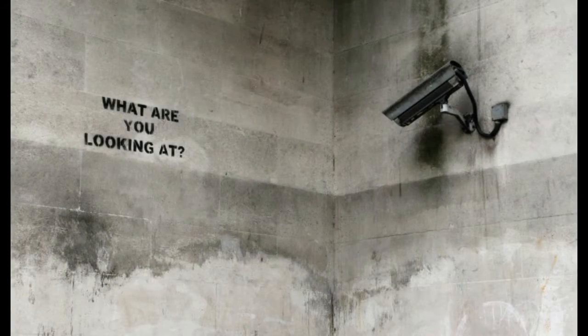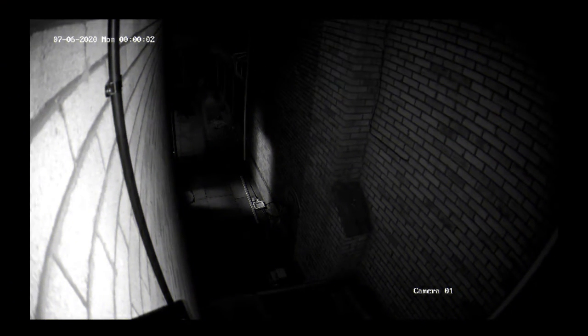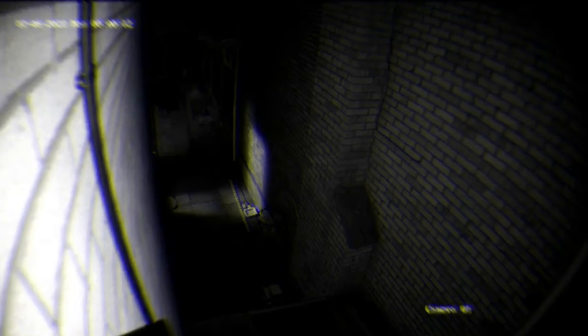Related to the angle, avoid pointing the camera to the wall where it is installed, even if it's just part of the view, as it can reflect the IR in night mode and do an incorrect smart IR balance, leading to a dark image stream.